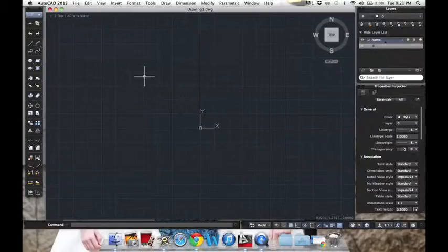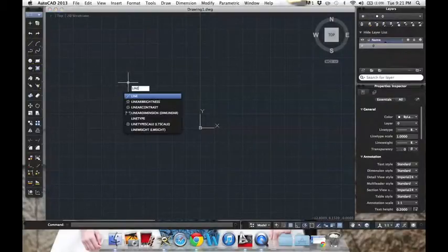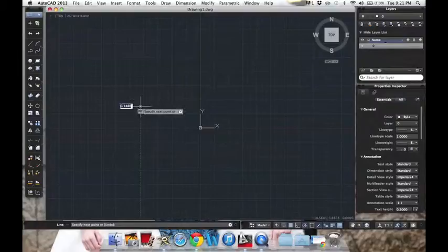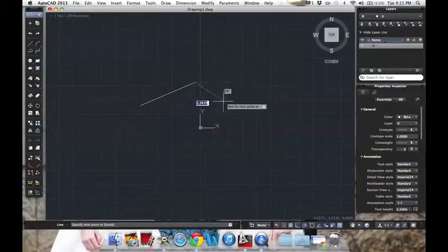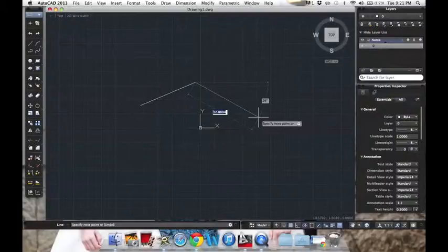Okay, so now we're going to work on creating extrusions from closed polylines. Now, if you want to use this panel on the side, make sure you are on the drafting pane. And you can either select the line button right here, or you can type in line. Let's do that. Line, enter. And let's just start by drawing a line. So we're just going to click where we want it to end. And as you can see, the line is continued. You can move it in any direction you would like. And it is going to stay connected to the previous one until you press escape.